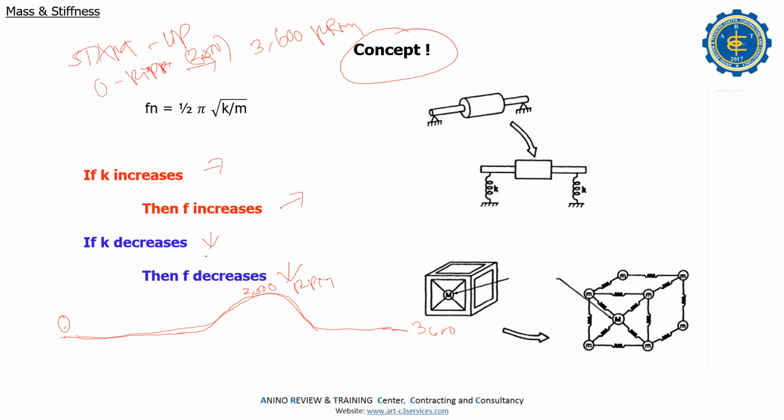After this scenario, the vibration goes down, and that's normal. Then what happens in the operation? For example, the running speed: if the speed is here and will pass by this critical speed, they must ramp up. They tell them to ramp up, make it a split of seconds. Meaning, don't stay in this RPM.